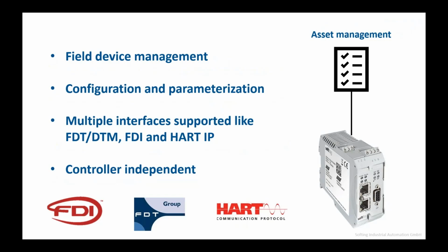Like there's FDI, there's FDT, there's also asset management via HART. HART offers a lot of asset management capabilities, and we included all those standards into our products, so you are able to connect your asset management system, might it be FieldCare or the different systems of different vendors.